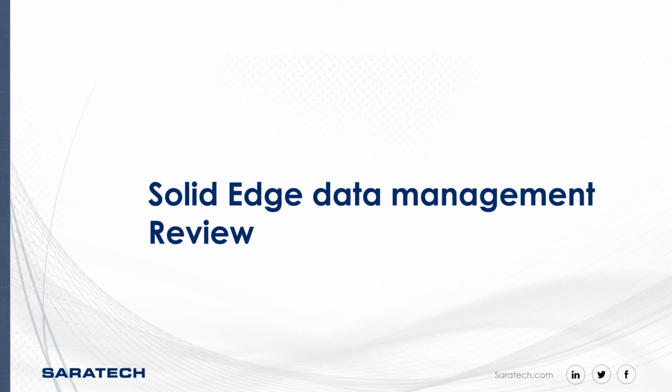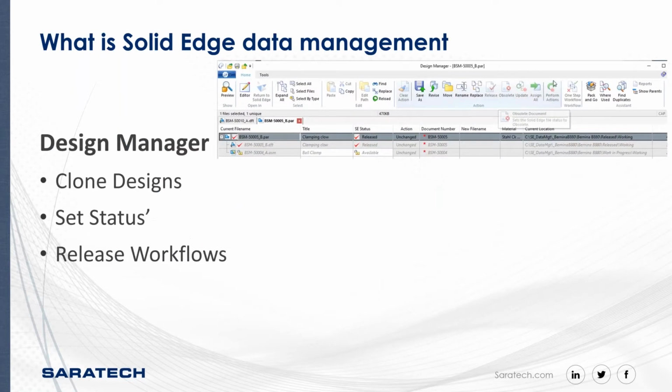So we're going to get into reviewing the previous session and what Solid Edge data management is. Inside of Design Manager, you can take advantage of the data management to be able to clone designs and set the status of parts that you're working on, as well as the person that's in charge of releasing these things would use this utility to be able to set the status and do workflows. We have additional capabilities in here with where used and replace, as well as copy and update things.